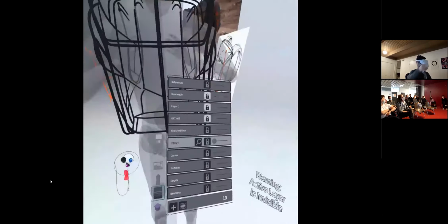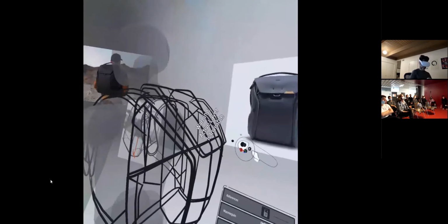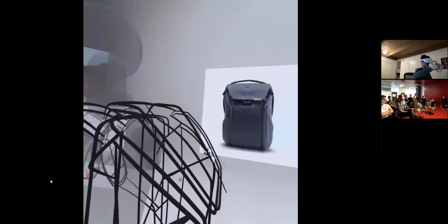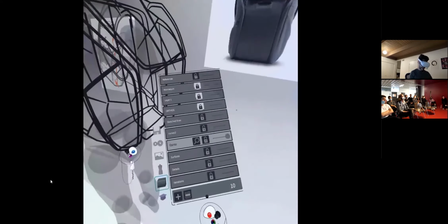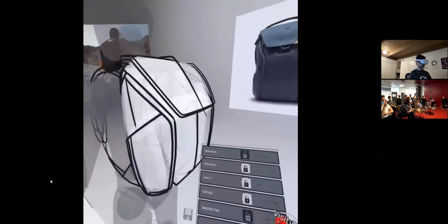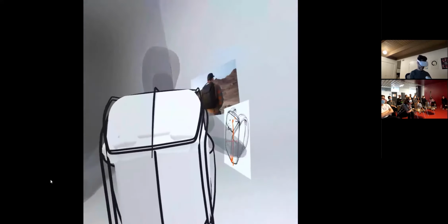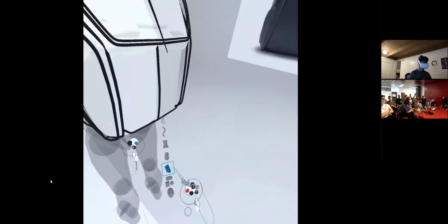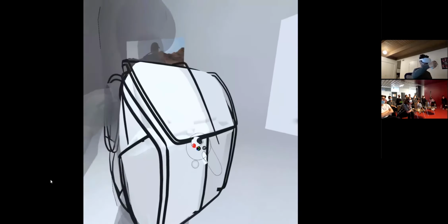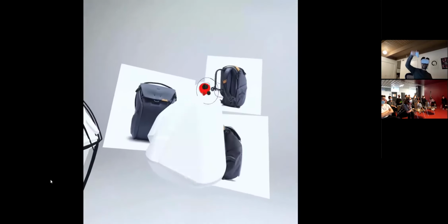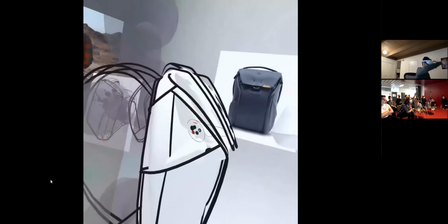Here's another tip. Once you have a wireframe like this, everything shows up at the same darkness if it's on the same layer. So what I like to do is fill it up with a white volume. And how you do that is with this volume tool. I just set that to white and literally fill it in. The way this works is you just start in every direction and it just keeps filling. So basically I fill it all in to make sure only the outer lines show up.